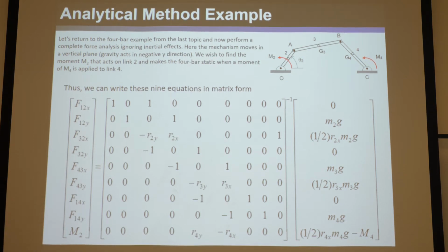Okay, and from those forces that occur at the joints, you could calculate what force is going through the beam or the link, and therefore you could know, are they bending, are they compressing or stretching too much, are they yielding, are they buckling, and you could use all your solid mechanics equations for beam bending and those kind of things on each of these essentially link-like beams, and load them and see if they're anywhere near yielding or buckling.